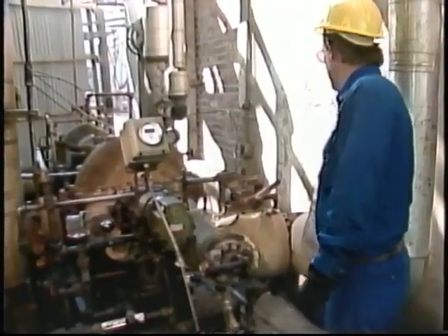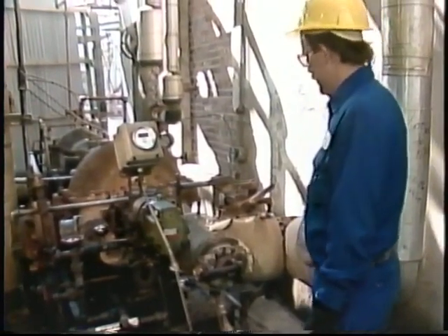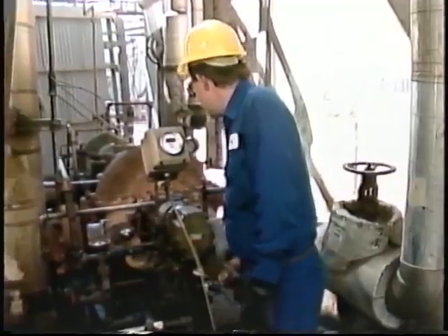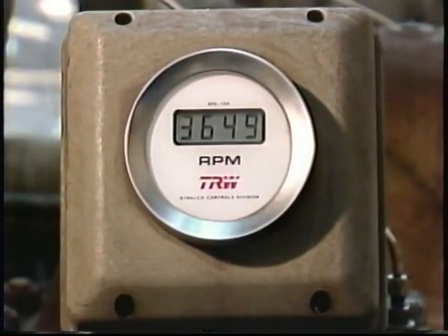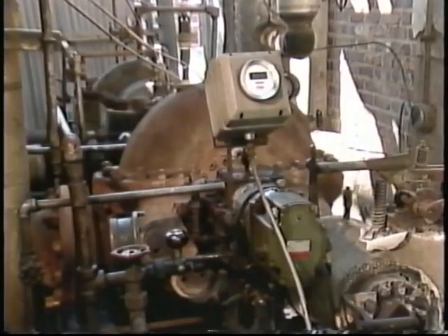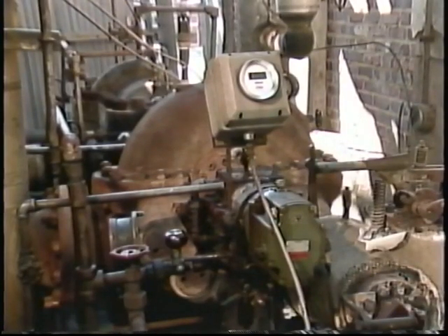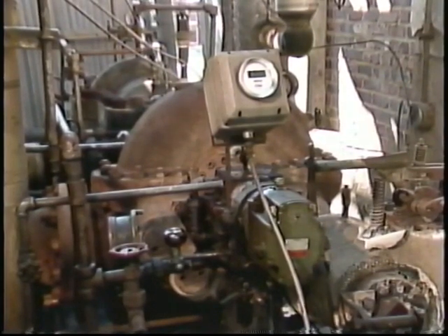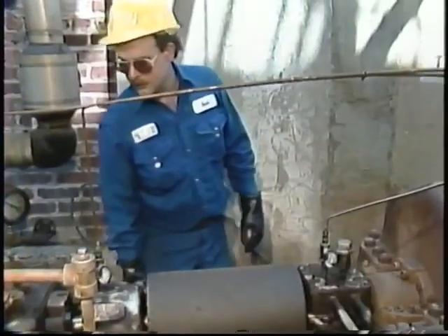While the turbine is in normal operation, readings of turbine speed help you judge how well the governor is working. The speed for the turbine shown here is indicated in RPM on a tachometer. Another condition that is important to observe during routine inspections is vibration. It's normal for some small amount of vibration to be present anytime a turbine is running. Excessive vibration, however, can be an indication of trouble.